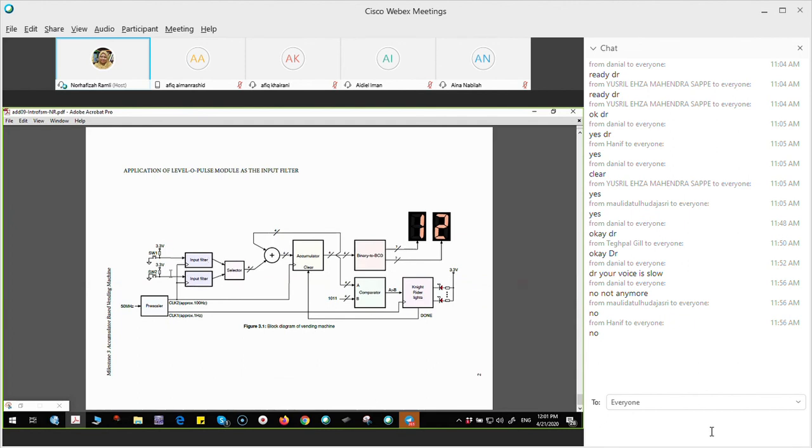This prescaler, on the other hand, what is the issue? Your eyes cannot capture 50 megahertz. That's too fast, right? So because it's too fast, you reduce to 1 hertz so you can see the changes here. However, 1 hertz is 1 second. What is 1 second? I think it's quite a long time as well, between 1 second to another second.